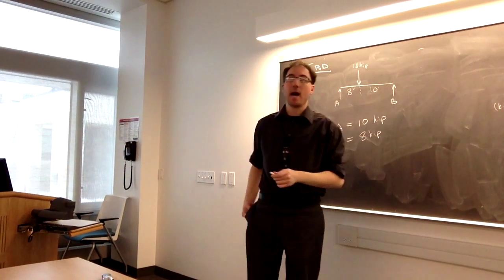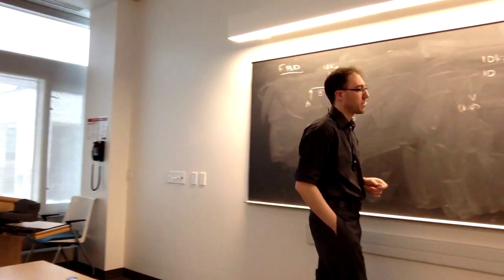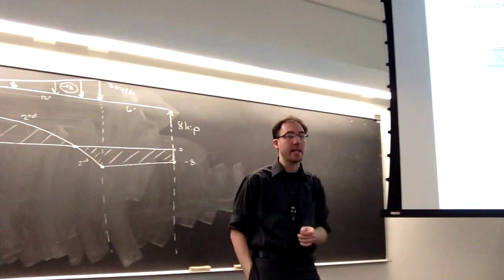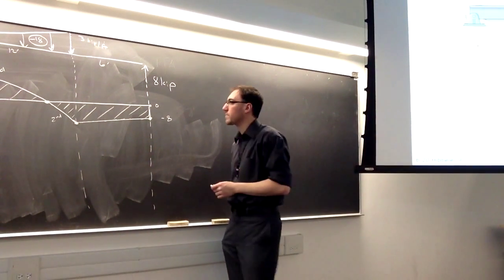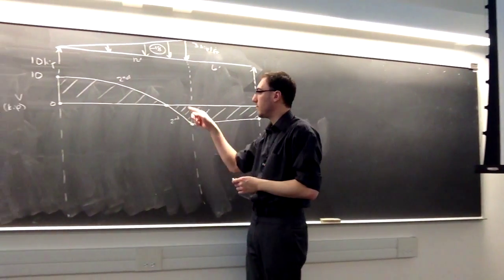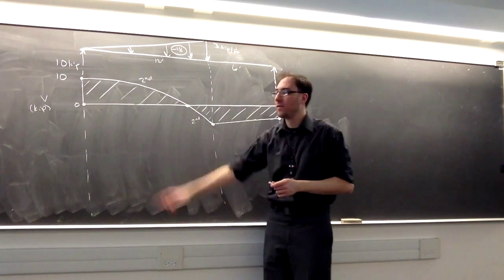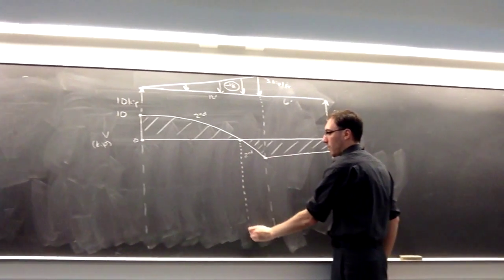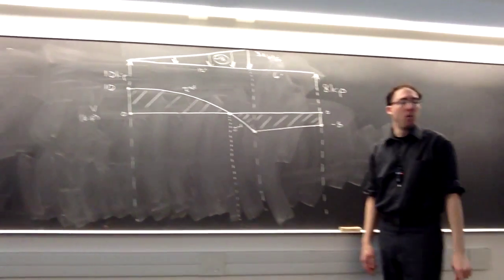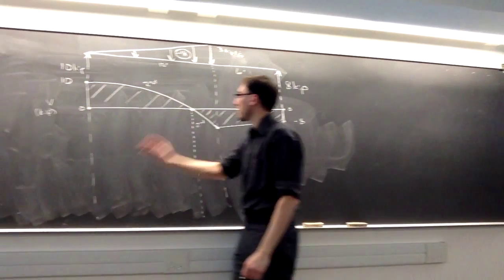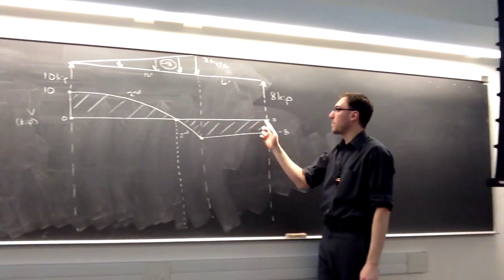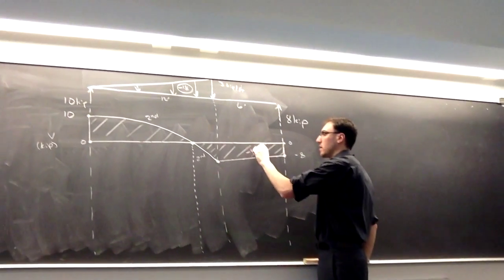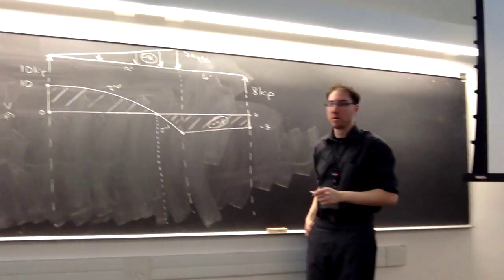So making the V diagram wasn't terribly difficult because it's similar to making the M diagrams we saw before. But now using the information we need for the M diagram is going to be trickier because we have to know the value under the V graph at all of these points. First of all, there's a 0 crossing, which will influence the M diagram. So we need to know the value under this part of the graph, and under this part of the graph. And then the easy part here where it's rectangular, it'll be -8 times 6 is -48. So that's the one easy piece here.